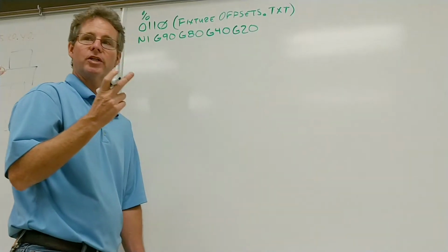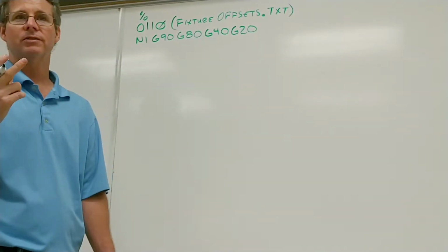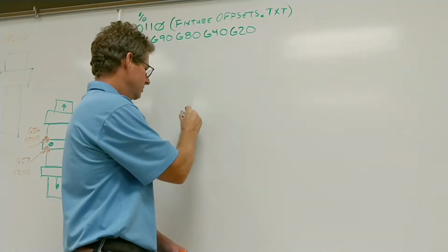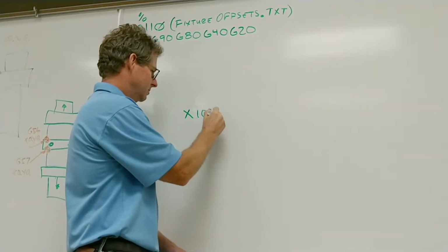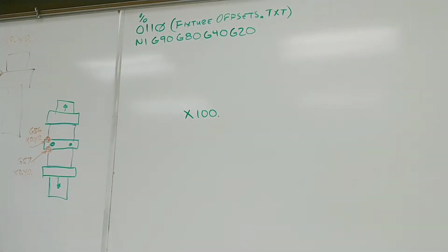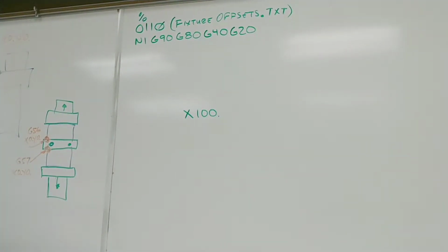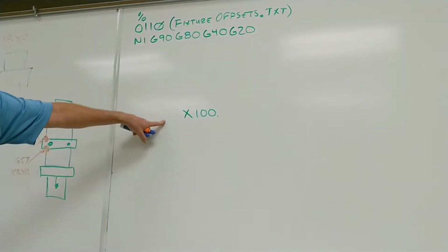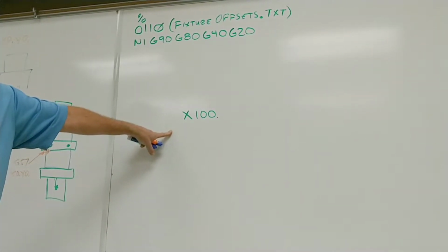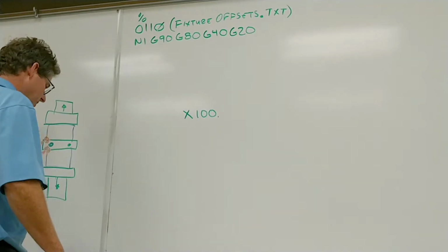Because a move of what is supposed to be about 4 inches, metric, right? 100 millimeters, doesn't go too well in the inch mode. Okay, you better hope you don't have anything mounted on the end of your table, because it's going to try to go through it if it's a rapid command. It's going to take it as 100 inches, and 100 millimeters is just a little bit less than 4 inches. Okay, so you don't want that to run.